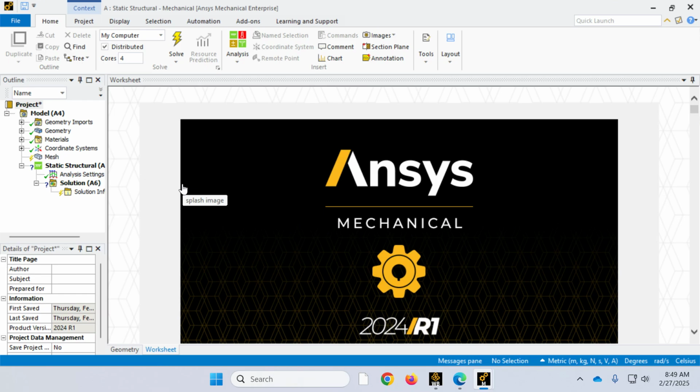The ANSYS beam element can handle tension, compression, axial forces, bending in beams, torsion of shafts, and the behavior of a frame element. But this is very different from a complex geometry that is not behaving like any of the above. It's not a beam, not a frame, not a truss. Then you're forced to use a 3D model. Right.